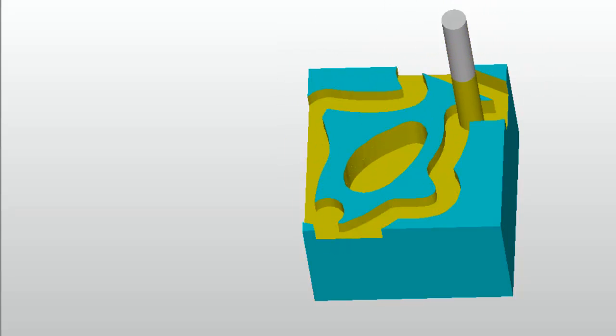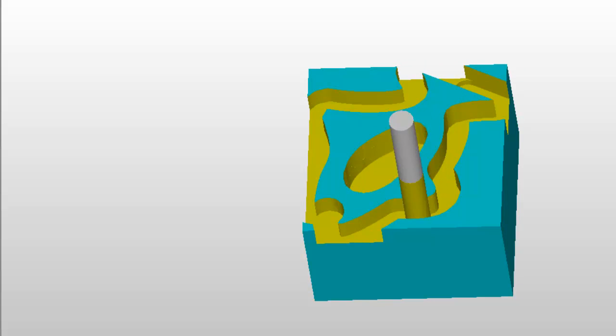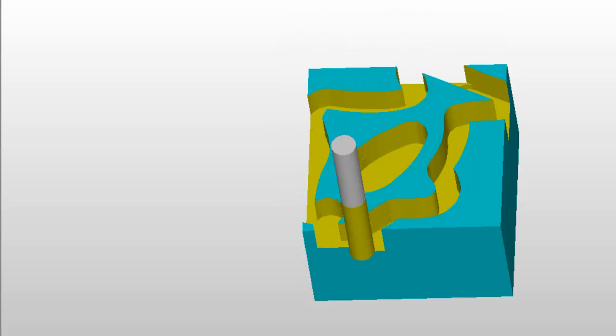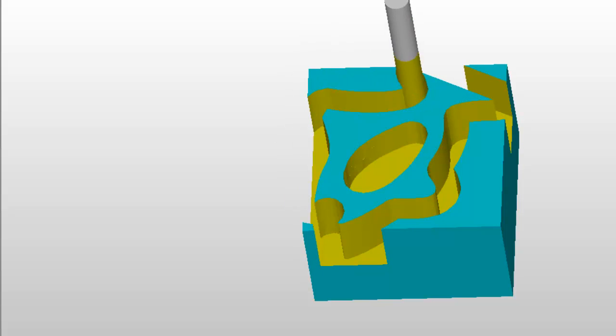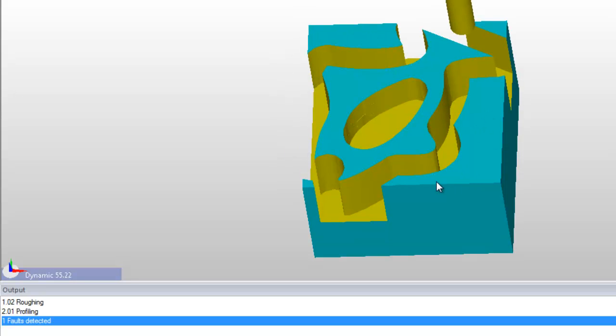I'm going to drag this to a little slower for now, hit play. Okay, drag it faster, get that pocket done, and now see, okay, it's cutting around my fish. Now the reason I didn't rough, if I used a roughing operation, what it would do is it would take off all this material too, which is just wasted time.